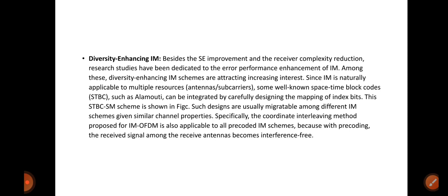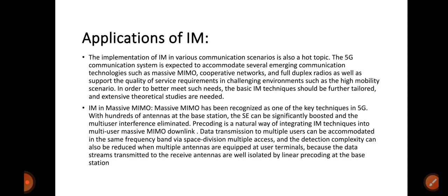Such designs are usually applicable among different IM schemes given similar channel properties. Especially, the coordinate interleaving method proposed for IM-OFDM is also applicable for all the pre-coded IM schemes, because with pre-coding the received signal among the receive antennas becomes interference free.